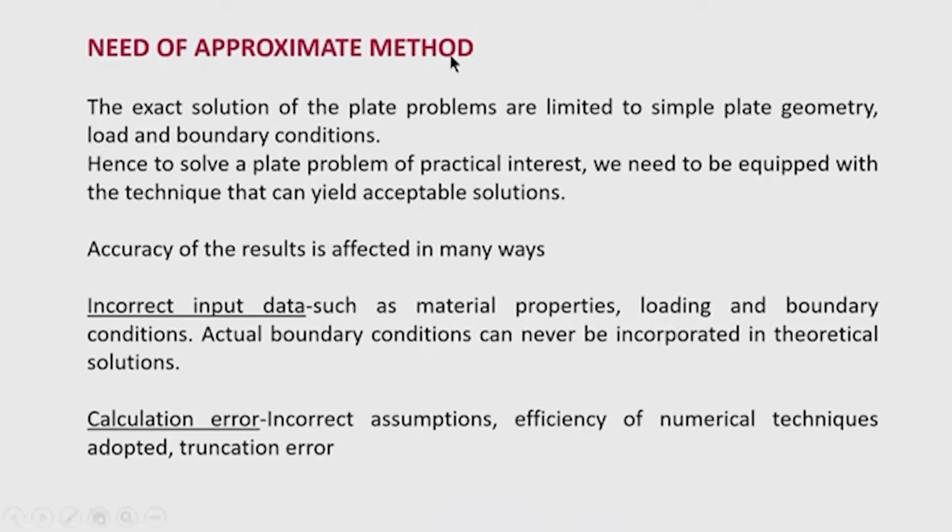First, let us see why we need the approximate method. The exact solutions of plate problems are limited. Why is it limited? Because the deflection that we have found is valid only for some cases with simple boundary conditions, that is, the simply supported condition. You have seen that the plate deflections were expressed in terms of a double trigonometrical series, which satisfies the simply supported boundary condition along the four edges of a rectangular plate.